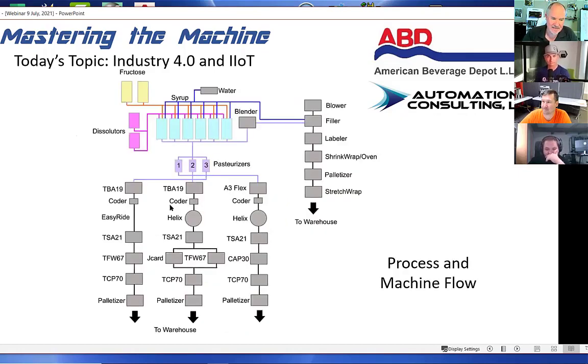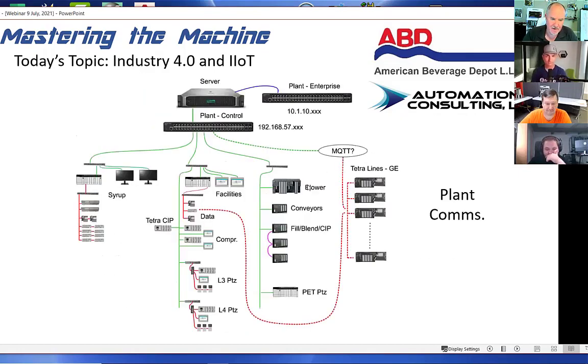And when you look at this, that's one of our problems here. A lot of GE, a lot of old GE, a lot of 90/30s. You cannot simply attach to those things and pull data out of them. I can modify the programs, no problem, but we've run into problems where when we tried to connect this directly, put an Ethernet card in there and just drill in and grab data out of it, it literally stopped the machines. And we don't know why. So that's one of our issues right now. How can we solve that problem?